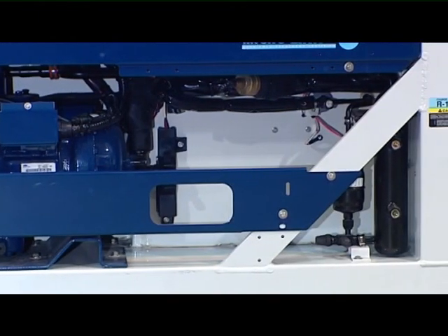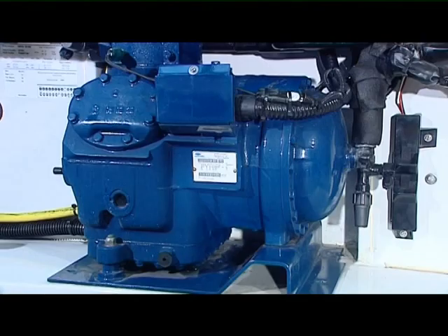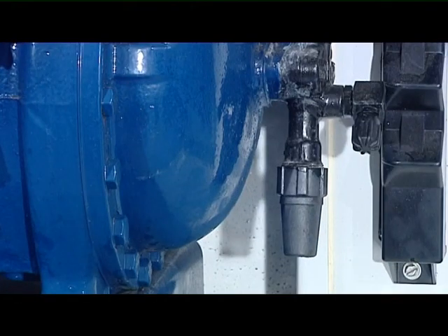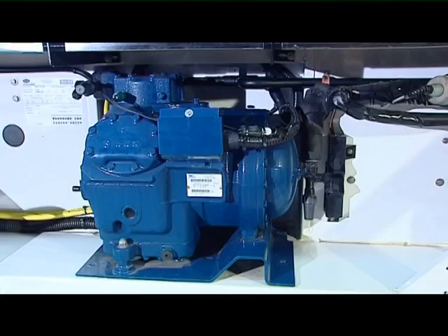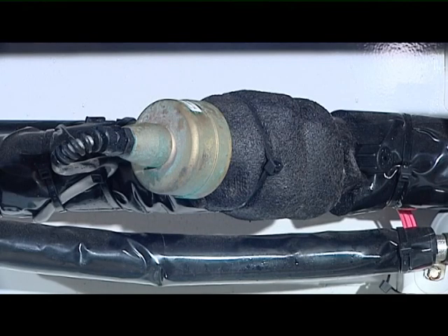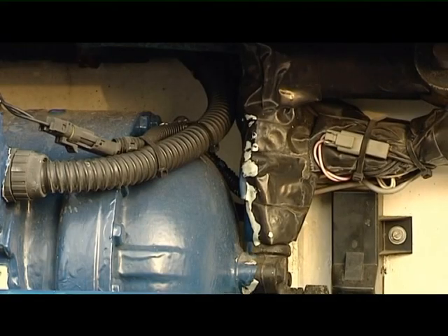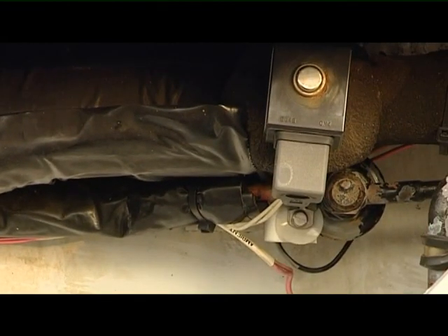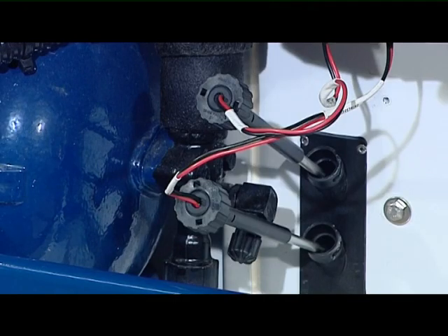The compressor section. The compressor section includes compressor, discharge valve, suction valve, high pressure switch safety, pressure regulator valve, stepper suction modulation valve fitted on the newer units, which replaces the suction modulation valve and the suction solenoid valve for the older ones, quench valve, and supply air sensors.